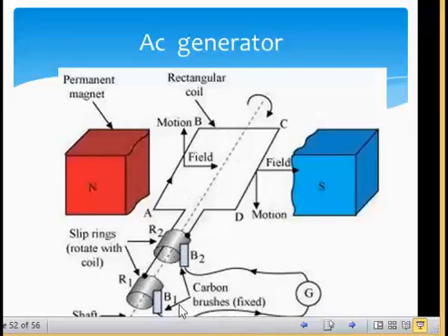Since the coil is rotating, if I connect a wire to get an output, probably to power my bulb, this coil is rotating, can't it twist the wire? So that tells us that the output is taken from the generator by means of carbon brushes and, of course, slip rings for AC. What makes an AC generator AC is that the output is taken using slip rings.